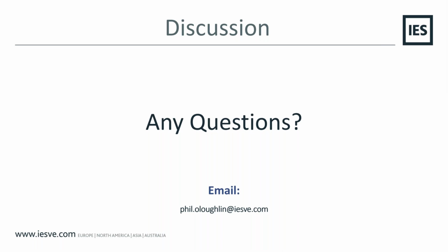So the first place I'd start to look is things like the CIBSE energy benchmark tool, which is available online, or the Better Buildings Partnership is another good resource, or even Landmark has the display energy data available. A little bit older is Guide F. I think Guide F might be 2012 now, but certainly a useful resource for information.